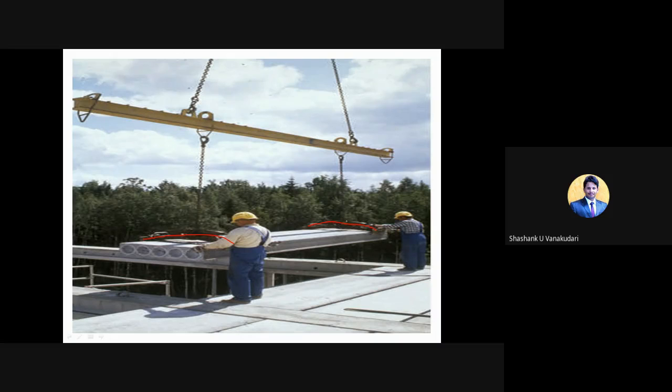So whatever stresses develop within these members initially are taken care of by these additional members provided on top of the RC planks. Okay, and then they erect. The only thing is what holds this particular portion. You can zoom in and see so that things will get clear. This portion fixes it properly, and whatever stresses develop within the erection members as well as the structural element are taken care of by this additional member, so that the stresses are reduced here.